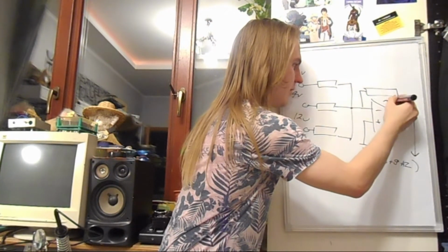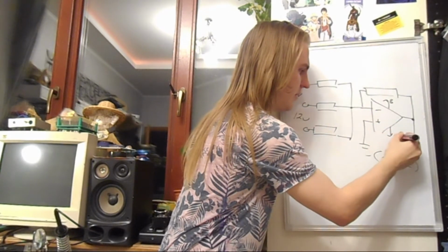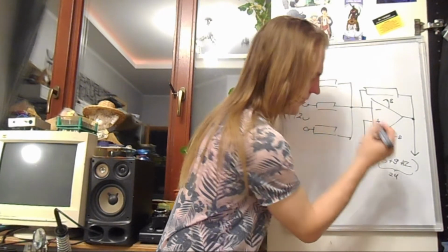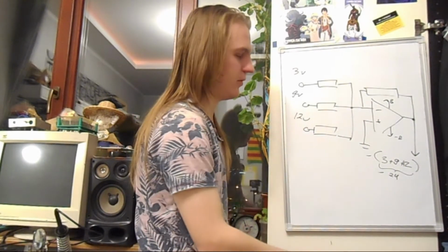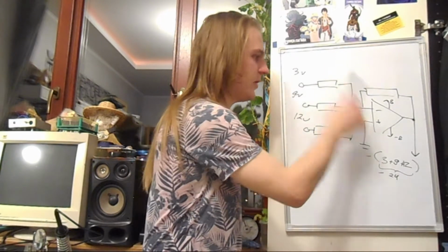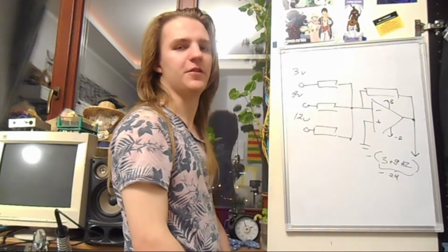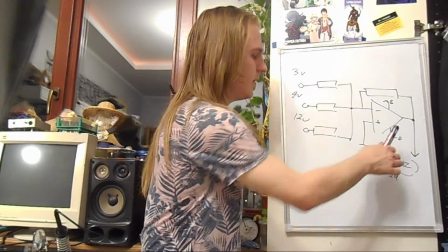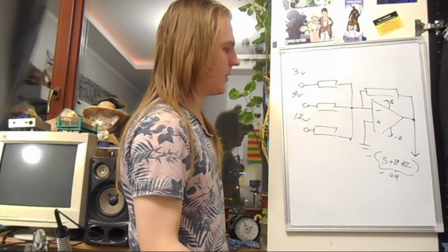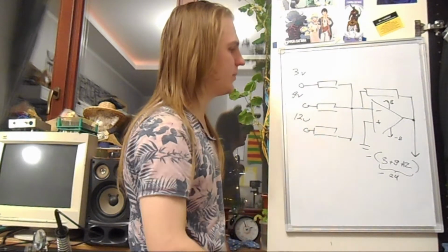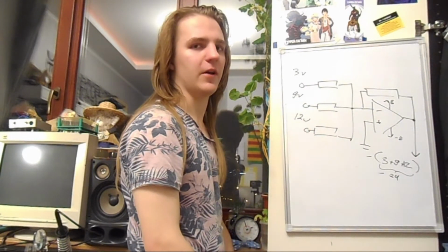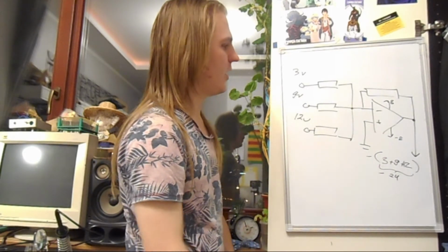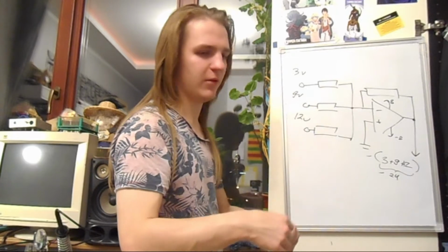So, say here we have 8 volts, and here we have minus 8 volts, and this is minus 24. Minus 24 is really lower than minus 8, and thus the amplifier will clip the output to minus 8 volts. So unless these three inputs result in a number that's not more than 8 volts or less than minus 8 volts, it will be clipped to these values because of the power supply.